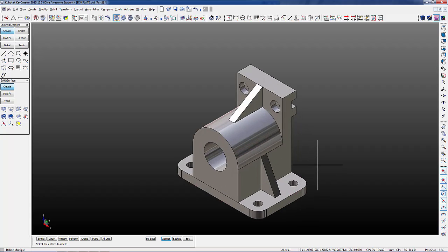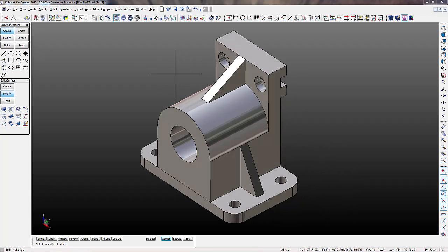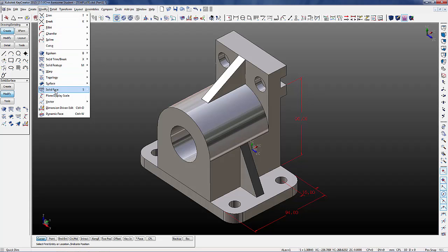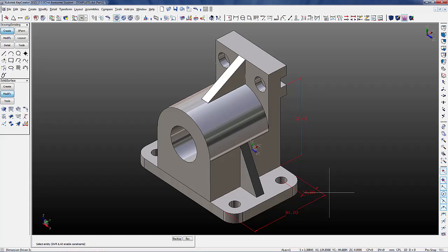Okay, I want to show you some additions to this model. Let's do some amendments here. I'll start adding some dimensioning here for changes. Let's grab this edge. That edge. Let's create some different situations here. You can change the plane to add the dimension in different planes. And now I'm going to use this powerful command, dimension driven edit. I can select this arrow and change the face, the opposite arrow, the face, and in the middle I can change in both directions. So let's start down here.